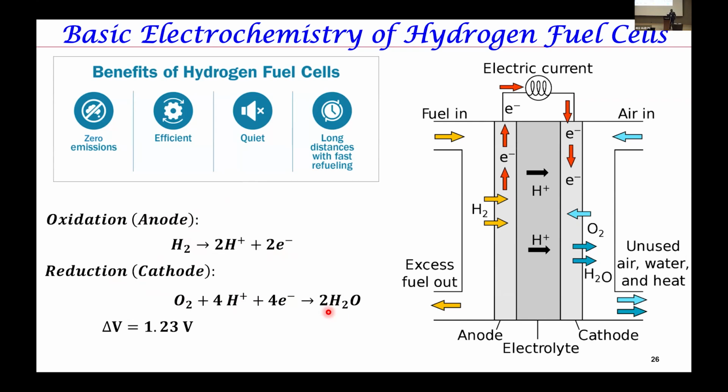Of course, you can stack the fuel cells and get more voltage, but each elementary cell gives about 1.2 volts. And this drawing here is quite complicated, but shows a variety of the species involved here. So you have hydrogen at the anode, which could come in as liquefied hydrogen, come in as a gas. Then that produces proton through the catalyst process. And then these protons travel through, and then they recombine.